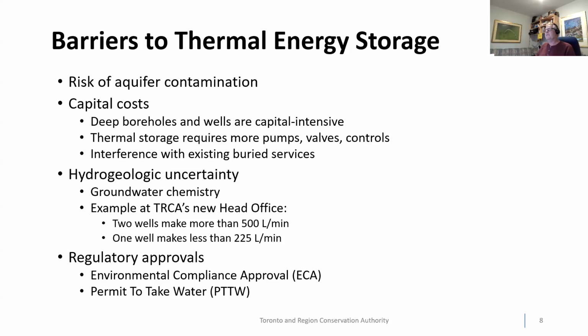And there's also the risk, with all these subsurface technologies, of interference with existing buried services. As you are likely aware, more and more, all our new developments have a lot of buried services, and more buried services are being installed every day. So we have to be careful not to poke holes through fiber optic cables, obviously electrical cables, and all the other subsurface infrastructure that's present in our communities.